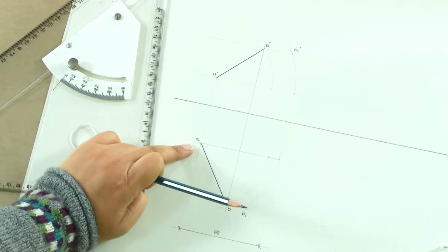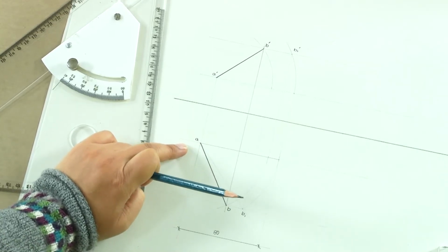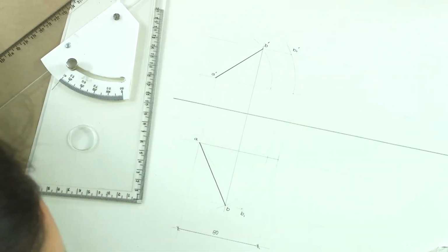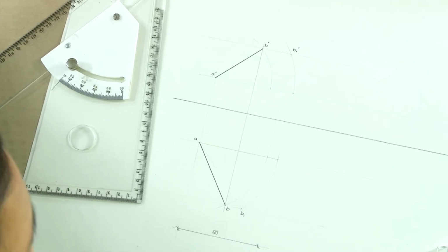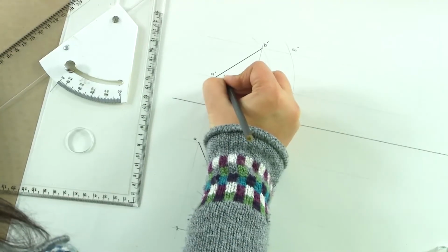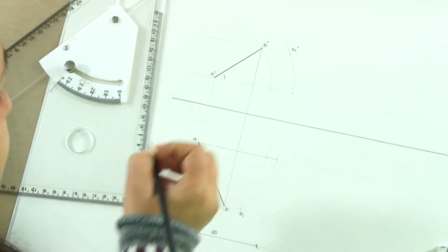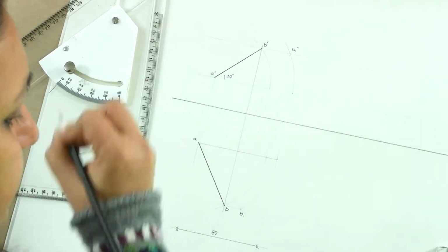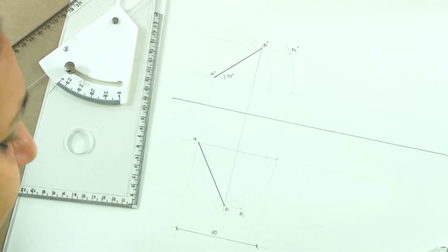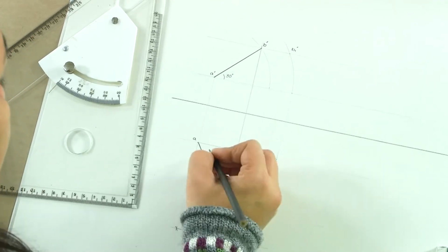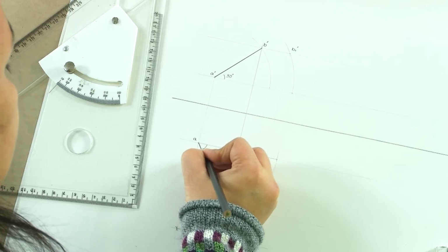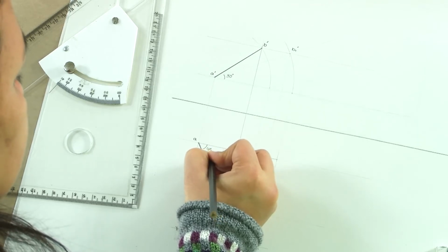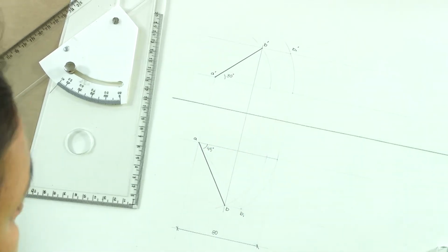The next thing is, it is making an angle of 30 degrees with HP. Now, we clearly know that this angle of 30 degree has to be shown in VP, assuming that this was parallel to VP. So, this is the angle 30 degree which it made with HP, and the angle that it makes with VP will be seen in the top view, which is 45 degree here.